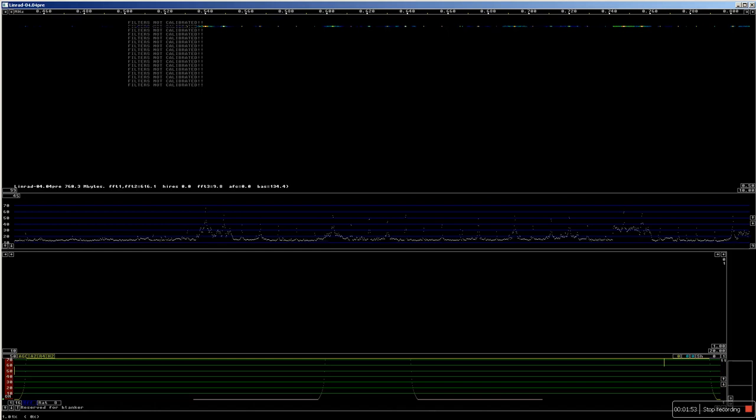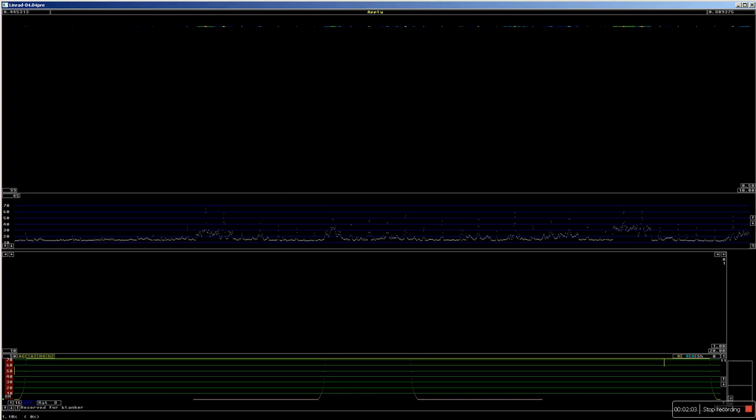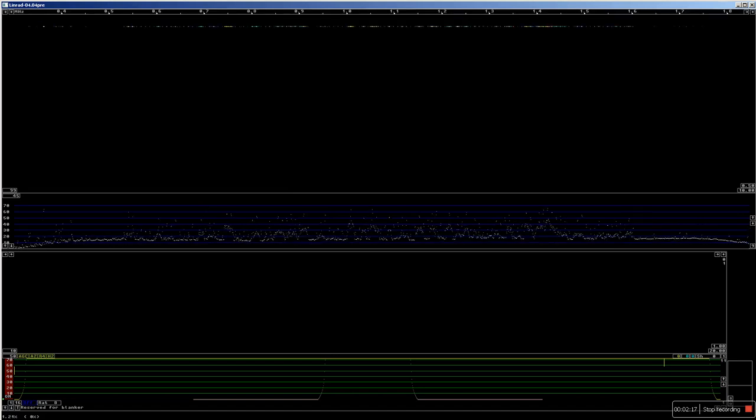And since I changed the FFT1 parameters, the scale has changed, so I click on the upper frequency scale to get this apply thing, and then I say I want from 0 to 2 megahertz, and then I click on apply here to get the entire medium wave band.